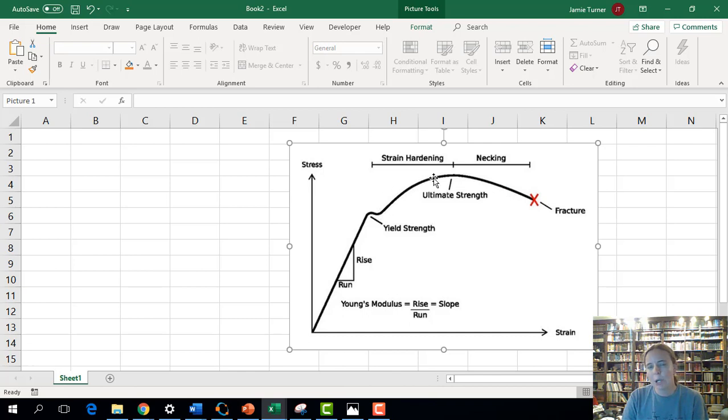And this is permanent deformation. So if I loaded it up with that force and I applied that big load onto it, and then I let go and I let it snap back, it would be permanently bent out of shape. It would actually follow kind of a similar curve back. So the same slope, but it would not snap back to its original shape. So we say that it's broken after this yield point.